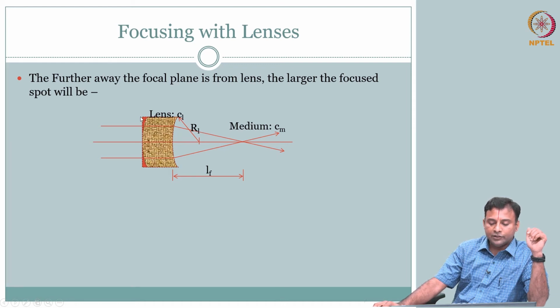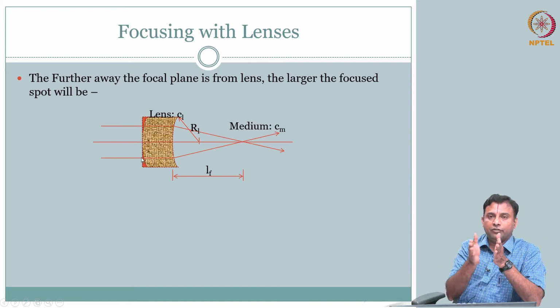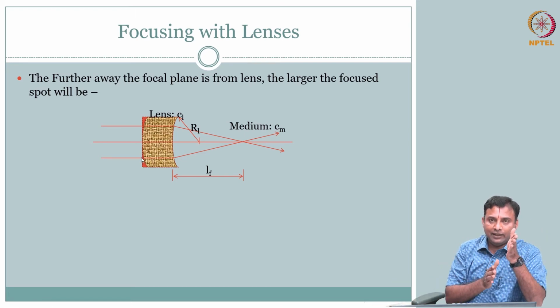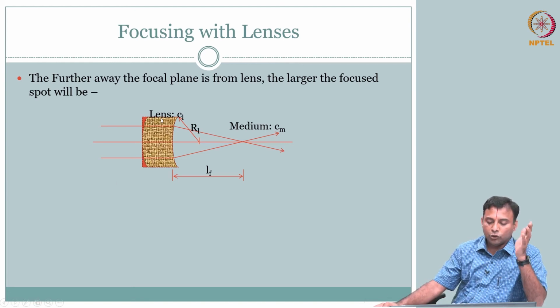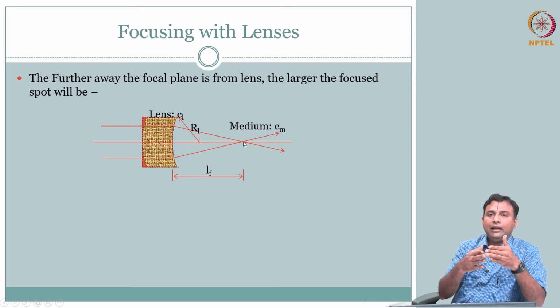So this is your transducer, the pink or orange that I have. At the front of the transducer, the flat disc, it was a flat disc. In front of that, I could have an acoustic lens with certain curvature R_L, and that can be designed to where you want your beam to be as narrow as possible.